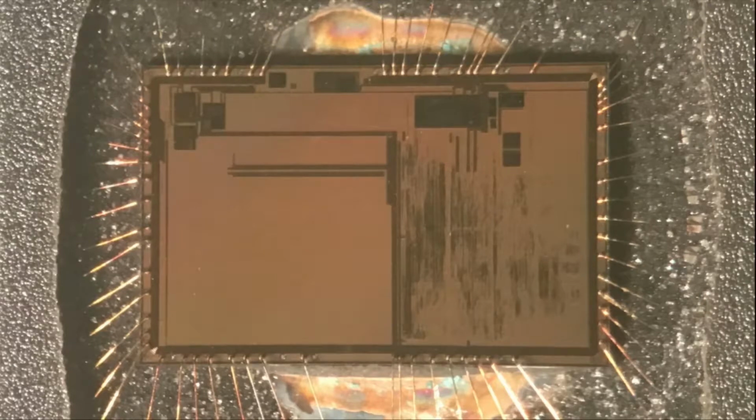So I took a look also just at the chips directly. I did a quick decap of the chips. This is an LPC 2148 chip. It's one of the older series of LPC chips. This one contains the flash bootloader, not the ROM bootloader. But generally, they're all still quite similar. They're all the 32-bit ARM chips.